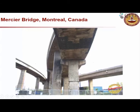And actually inside these girders, there were also cases where a lot of water gets in during the winter, rainy season, and then it just settles there. And also we get a lot of chlorides during the winter. They put chloride on this bridge so that you can actually drive during the winter, because it's too cold and then ice starts forming on the concrete surface. So to melt that ice, they put chlorides. Anyway, the problem is that chloride slowly penetrates into the concrete and then corrodes the steel.